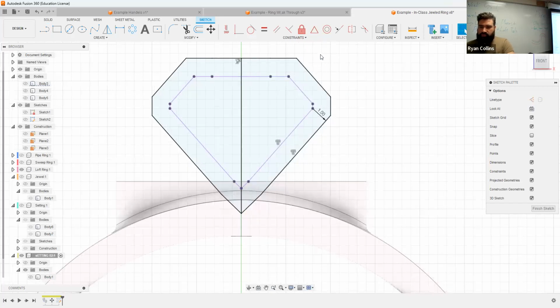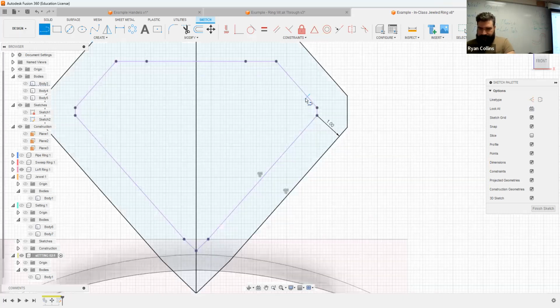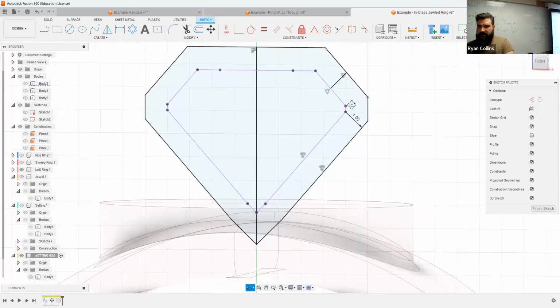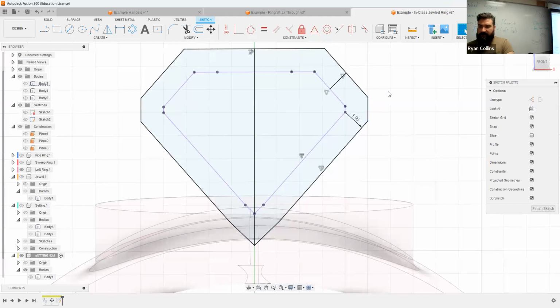And something again, sort of like there. Mousing over the projected line, I get close to the center. There we go. My center line constraint pops up the triangle. Now I can go out perpendicular, center. Nice.